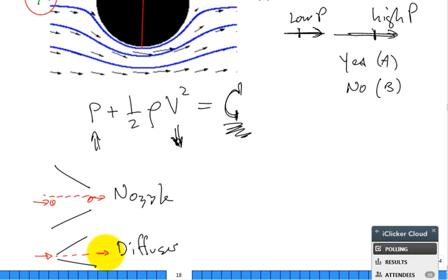What's the pressure doing? Recovering. Now, you got to be careful when you build a diffuser. A nozzle, you can make it pretty steep in closing that cross-sectional area. If you have a diffuser, you better take your time. Otherwise, what's going to happen out here, you're going to get separation because fluid flow doesn't like to go that way. It's an adverse pressure gradient.